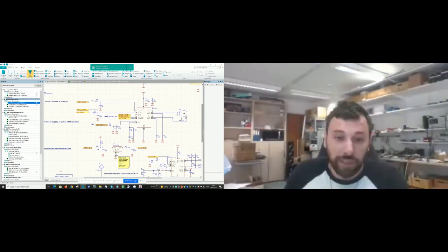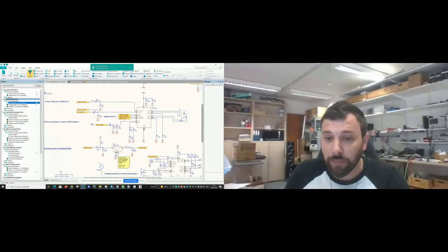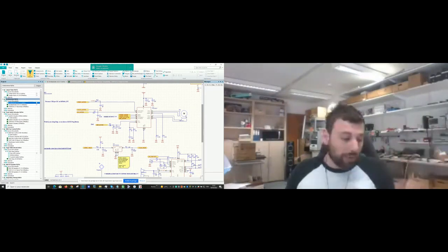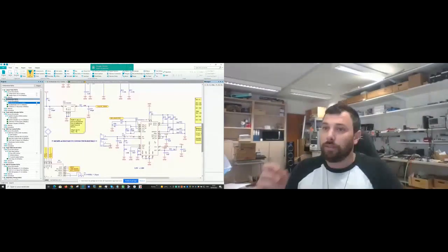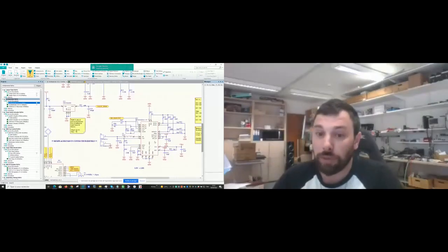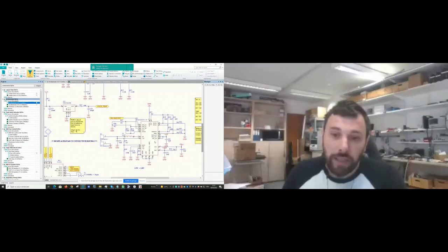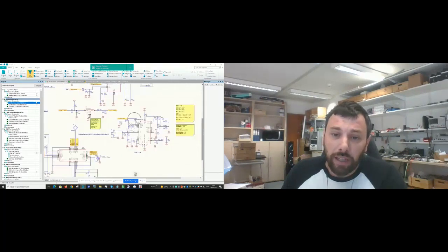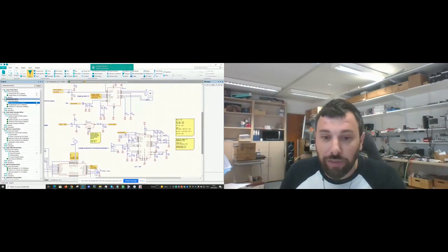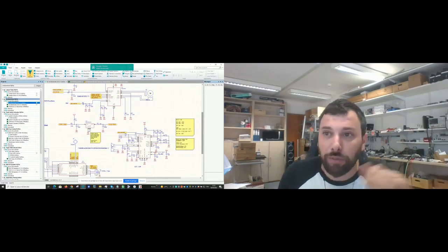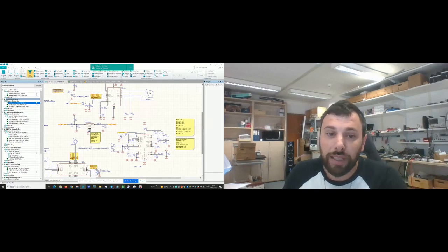Also, very important, we have a connector where we connect the Peltier element, and electronics that are able to take out very low energy, starting from some microwatts. This is a little more complicated part, to gather some energy from the Peltier element as microwatts, and this device is able to do it. It's even able to start with very low voltage.